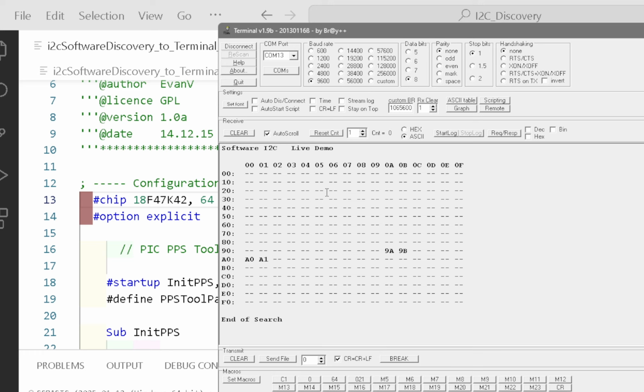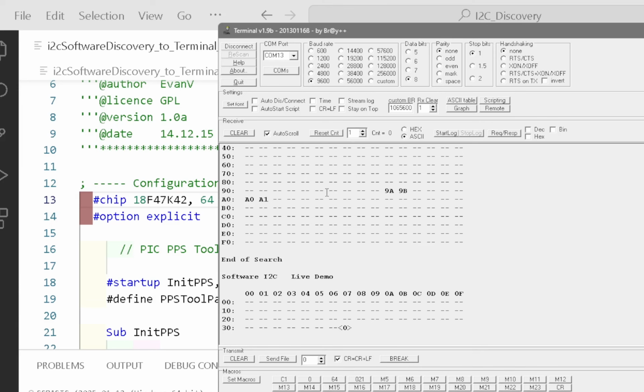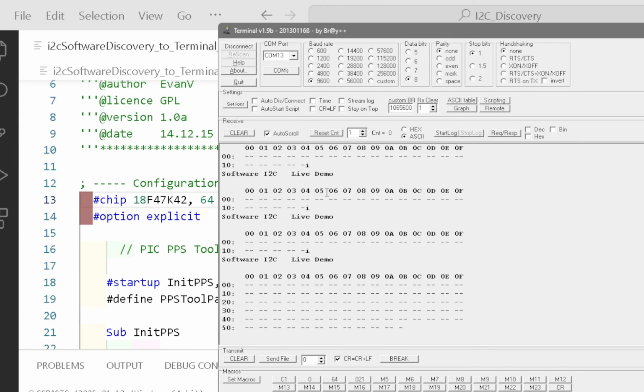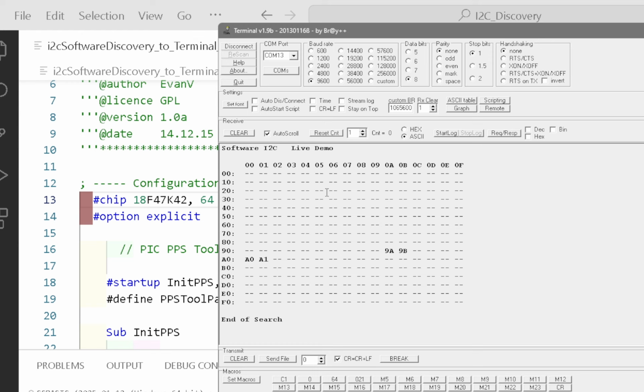It's because the bus is going too fast. Okay, if it works, it works. If it doesn't, just drop it down whilst we're doing this testing. Oh, it works fine. Okay. So always put it to 4 just to check everything's okay, and then up it. We now know that the I2C bus is pulled up high. It must be because it's coming up and down low. We got addresses responding. Fantastic.